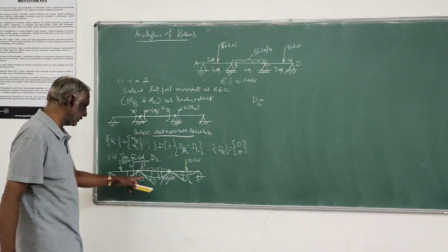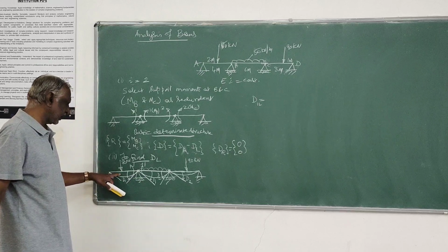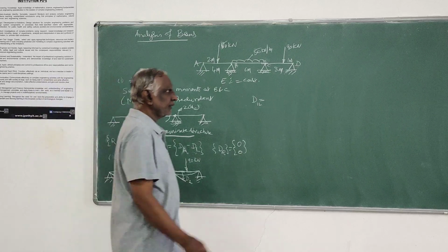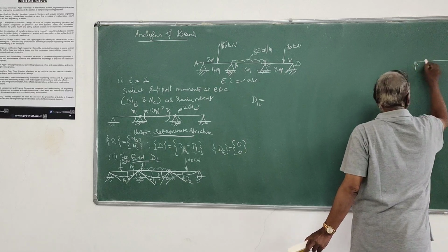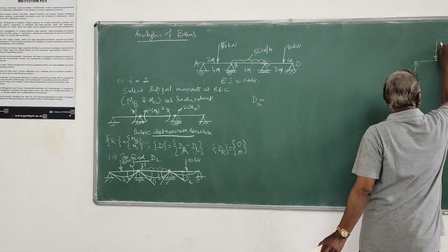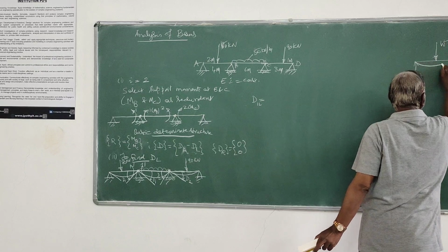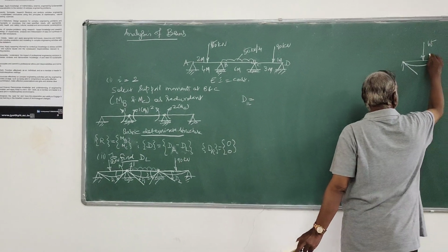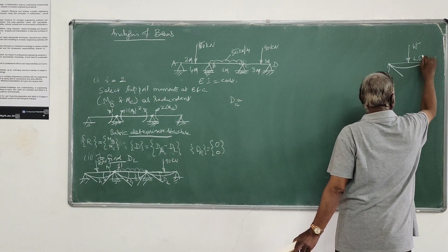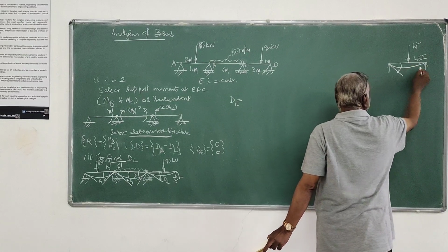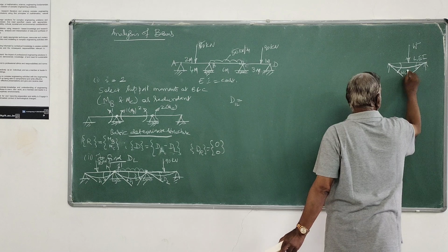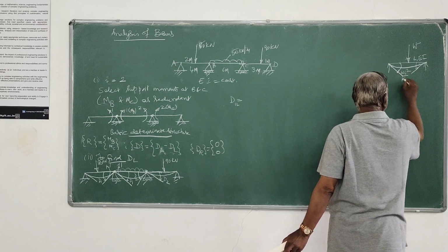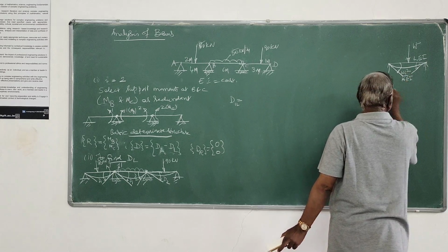So therefore, this D1 or D1L along coordinate 1, whatever the displacement due to the load, will work out. For this particular load, as I already told, if there is a concentrated load W given here, its span is L, flexural rigidity EI, the slope at these ends will be equal to WL squared by 16 EI.